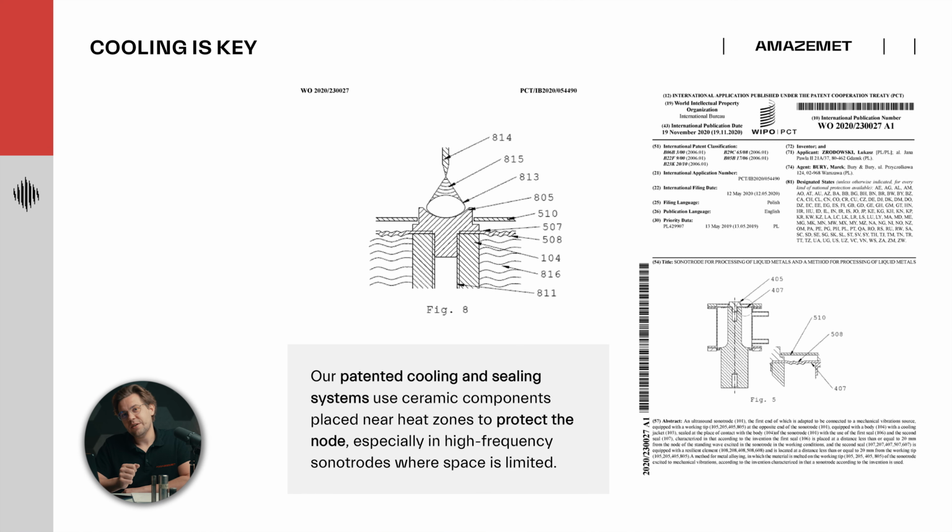Right now in the slide you can see one of our patents. It is related to the cooling system and sealing system of the Sonotrode cooling part. Basically, we're trying to keep the sealings as close to the antinode, as close to the heat-exposed part as possible, to keep the middle part as cool as possible. Then it is possible to keep the ultrasonic frequency within the limits of the transducer and avoid too much heat exposure, cracking and damping.